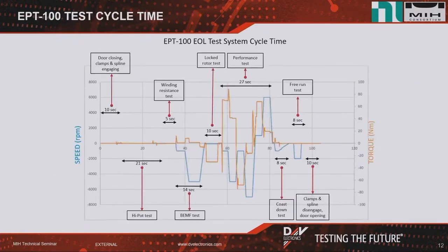So, as I mentioned earlier, if you want to run all those tests, that entire test sequence can be programmed. So everything from the hipot test to the free run test, including performance tests, could be done seamlessly. You saw the scripting tool that allows you to do that. This could be set up by us or some standard profiles, or the customer can create their own profiles based on their requirements and their knowledge of their system.